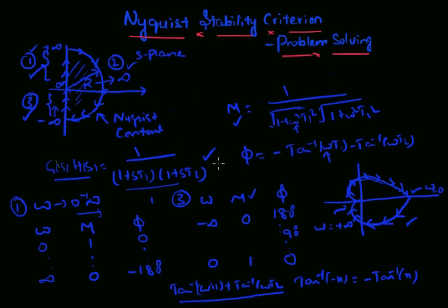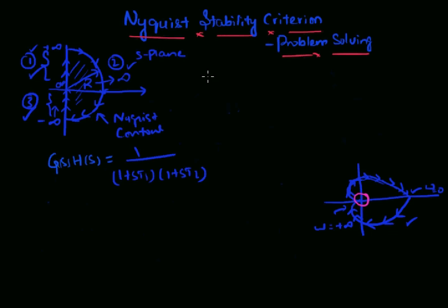Now what happened to the second section of the Nyquist contour? Where did it map from? If we look at it carefully, when r tends to infinity, the whole plot is going to be around this point, which will be nearly at the 0 section. Let's zoom into this area and find out how this plot is going to be converted when we substitute the values of this semicircle into G(s)H(s). Let's look at this second section, and it is going to transform like this.